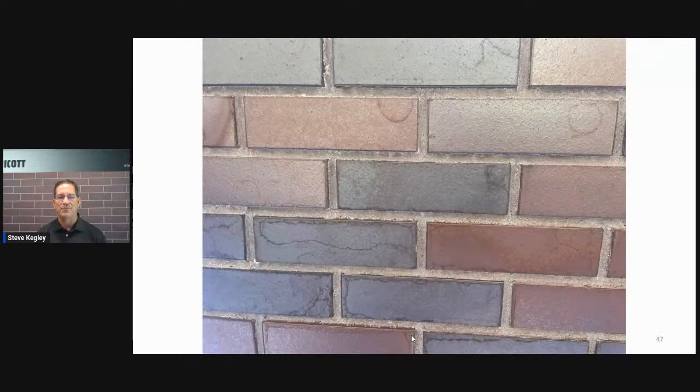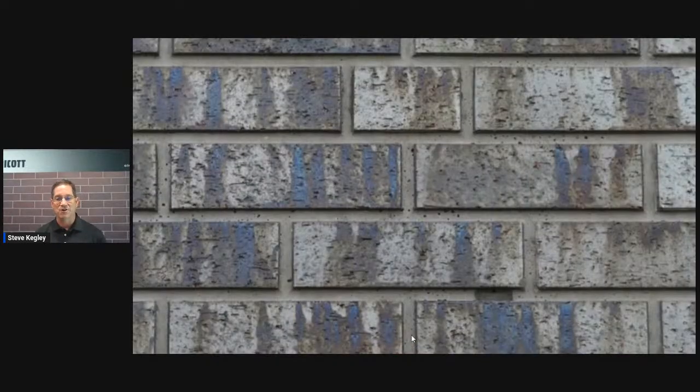Again, application here where you can see some of the leftover residue from the retarder or the releasing agent or whatever. And then again, when they cleaned this, they didn't water it all the way down to the bottom of the panel with a lot of water. So therefore it started drying. It must have been done in the summer, spring, fall, or whatever. We can see that it's kind of dried on there. So another best practice is cleaning that brick thoroughly.